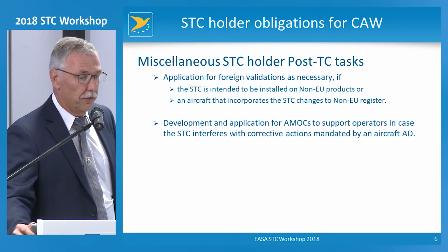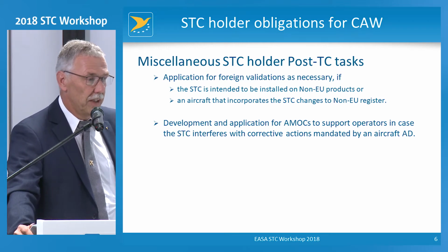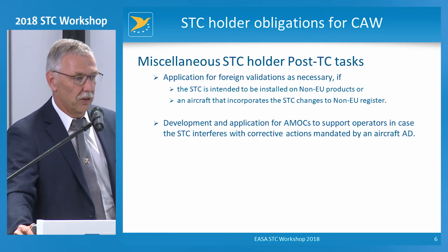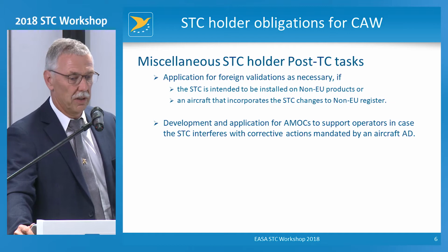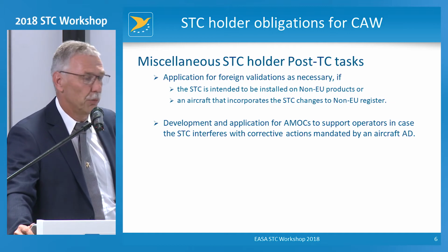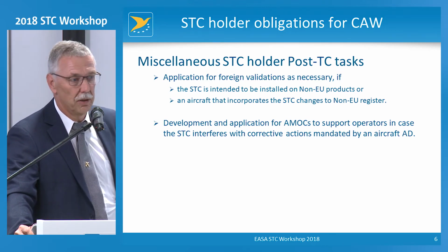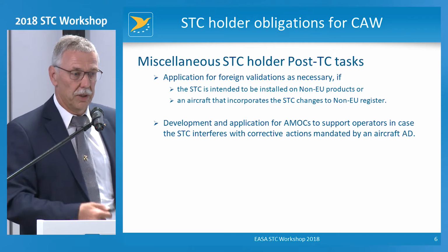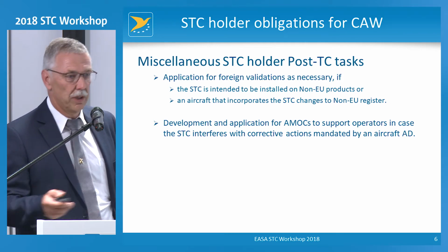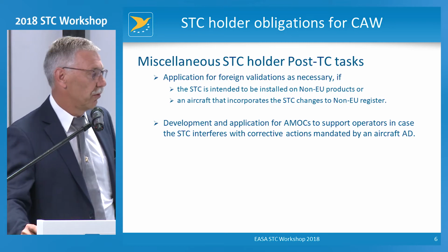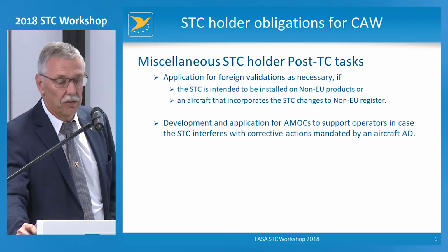Further on, if an STC is installed in an aircraft and an AD on that aircraft interferes with the STC, or the other way around, there may be an AMOC developed just for that specific aircraft. It happens sometimes if electrical systems are changed, and then probably the basic aircraft has a major upgrade of its electrical systems due to problems discovered in service that need adaptation.